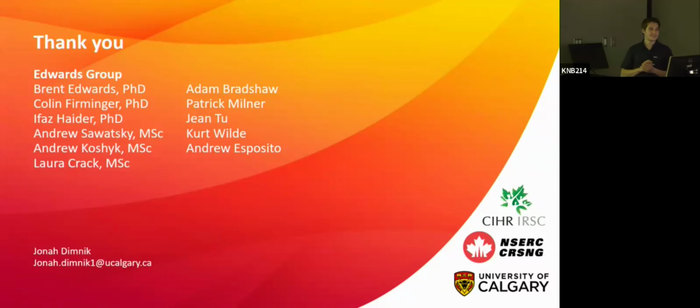Can I play devil's advocate? I've thought about that, but when we do a material test and we cyclically load it, no matter how much damage is incurred, the apparent density stays the exact same. Roughly the volume's not changing, right? But the stiffness is degrading. So that tells me that you would have a different relationship between density and elasticity if you have damaged material versus undamaged material. But isn't that what your model is all about? That's what our model is for.